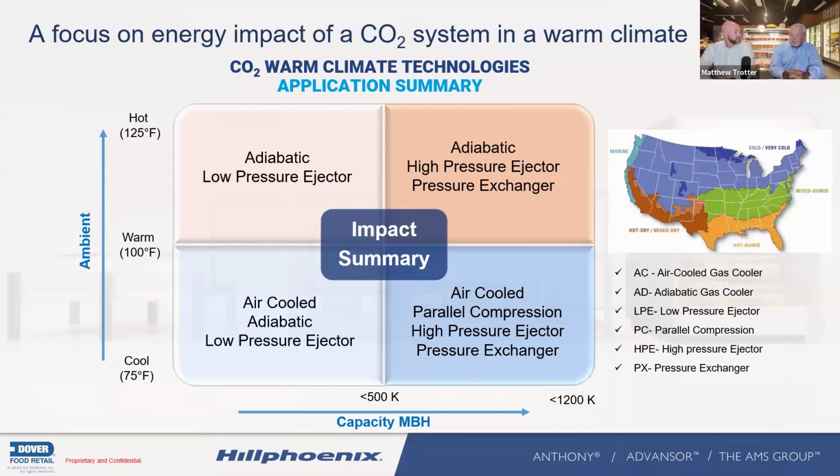Yeah, and the other thing, when you look at how we look at energy within a system: you could have an HFC system, an HFO system, traditional, with air-cooled condensers, no energy efficient fan motors, a mechanical valve, and just regular on-off compressors. Okay, and you use that as a baseline. Then you go to adiabatic, variable speed motors, unloading on your refrigeration system. All those things in themselves make that system more efficient.